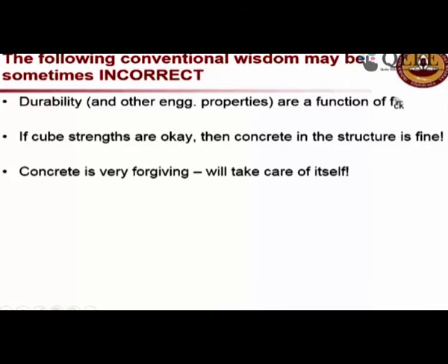We do not normally talk about the permeability, chloride resistance, carbonation resistance, etc., of the concrete. In most cases we look only at the strength, and we assume that if strength is better, then everything else is going to be good, which may not be true all the time. Another belief is: if cube strengths are okay, then the concrete in the structure is fine. Again, this may not be true all the time; we may have to look at other properties as well.